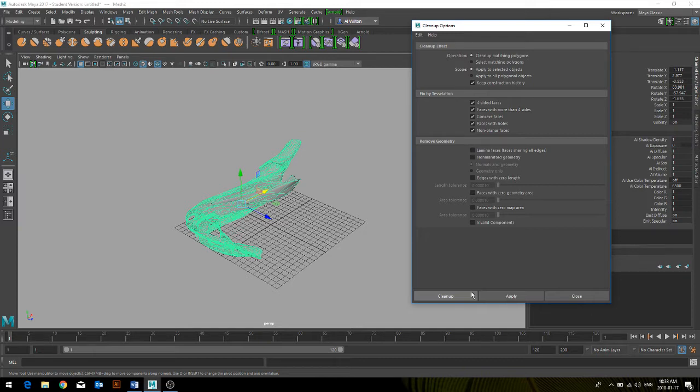Because it's maybe a time-consuming process, sometimes it makes sense just to say, okay, my scan was not perfect, let me go back to recap because it has access to my original file. It may be a bit cleaner. So edit your geometry a little bit there and clean it up, reduce the faces, and then bring it back to Maya and just start manipulating without reducing the meshes, the polys. Because sometimes it is doing some weird stuff that you can't really find an easy way to fix because it was a machine producing a 3D object for you. It's not a very clean mesh. There are some tools like the mesh cleanup and the reduce polys and the recap to address those issues, but sometimes it may not work.